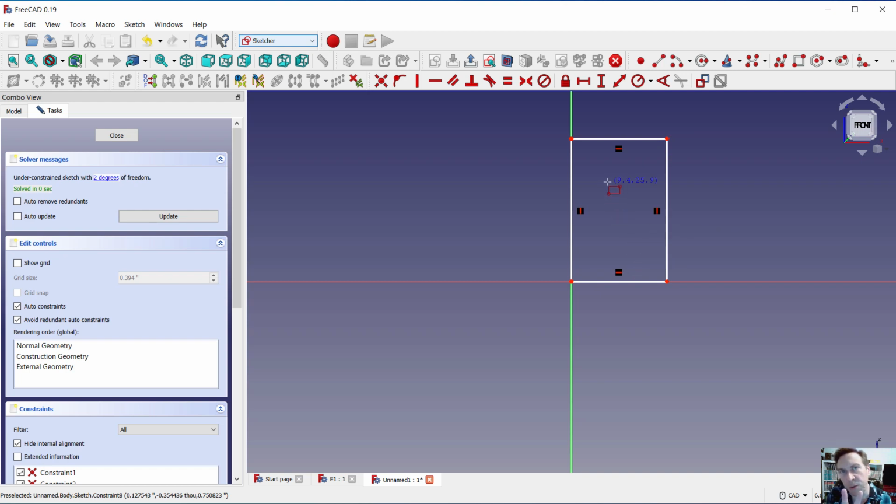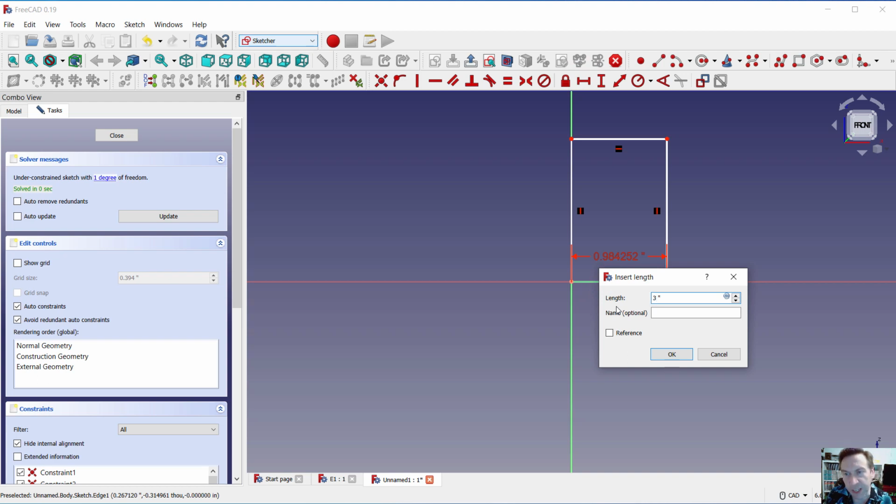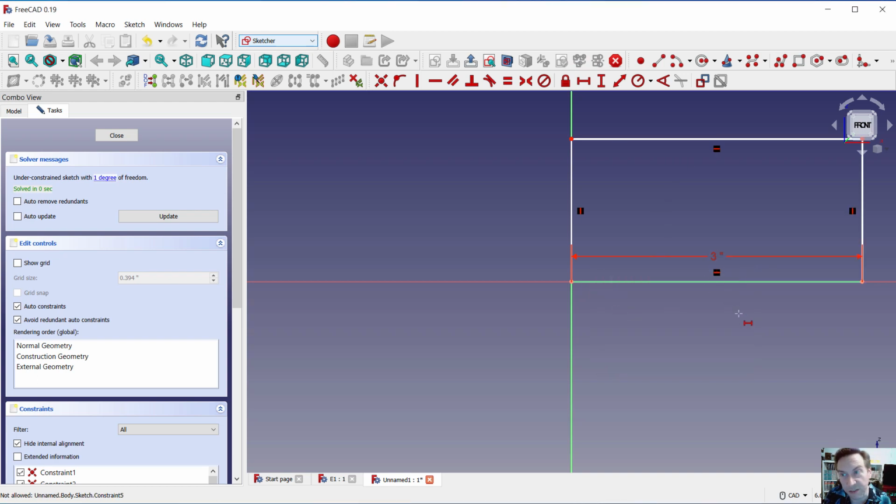You'll see little symbols. Those are constraints. There's 2 forms of constraints in this, just like most modern CAD systems. It's basically you have dimensional constraints, which is like length, width, things like that, diameter. And then you have, in this case, vertical, horizontal, and over here we have a bunch of them, perpendicularity, parallelism, a bunch. Those are common elements of geometry, just to clarify that. Now let's go over here. This enables you to put in a horizontal dimension. So click on that, just like on the bottom here, and type in 3, hit enter, and it will extend it to 3 inches exactly.